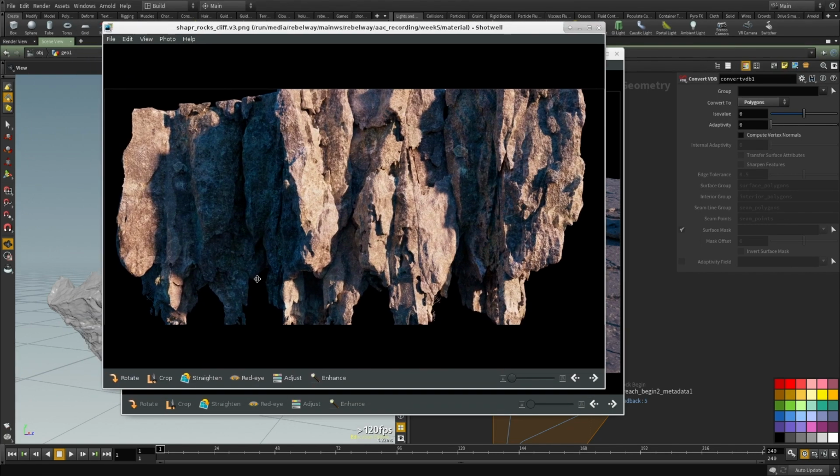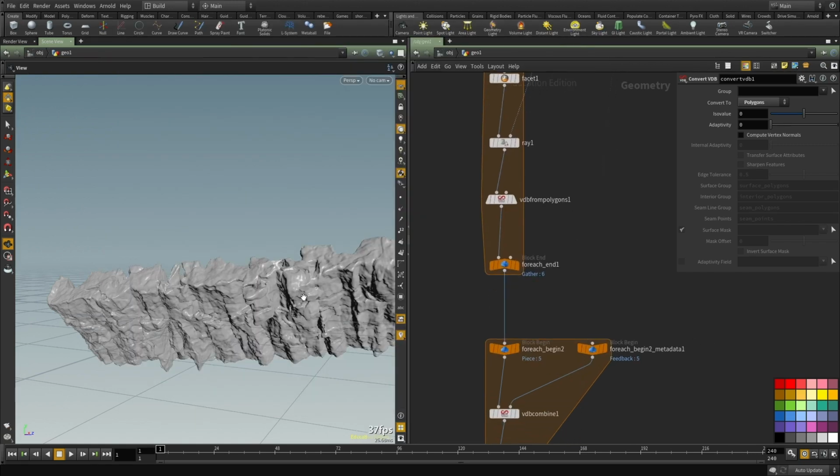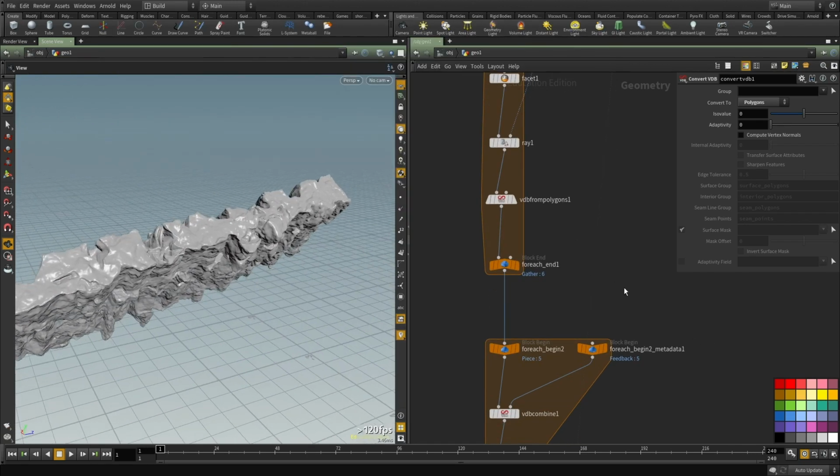This geometry had some issues, and I fixed it with this method. And it's going to be very important when we start creating the low-res meshes for in-game. It's very important to have a clean mesh with just the outer layer. And this is the method to use. Hopefully you guys learned something new and like this.